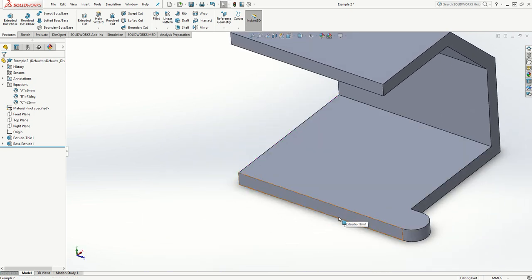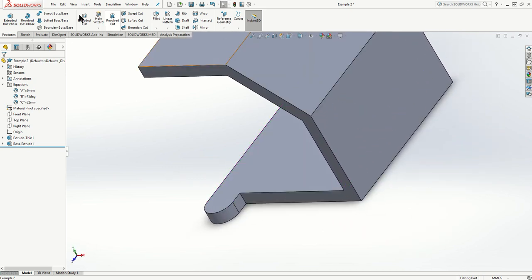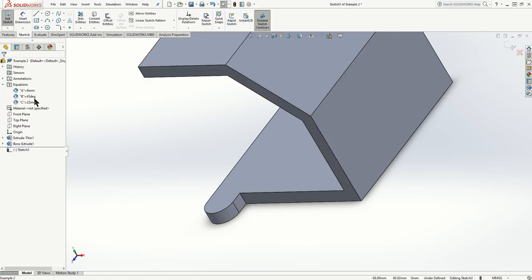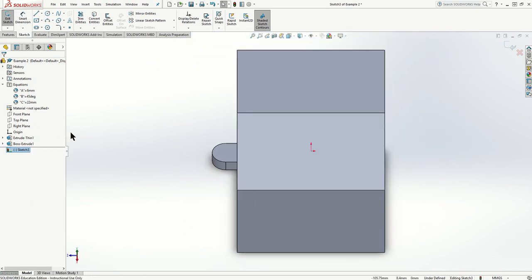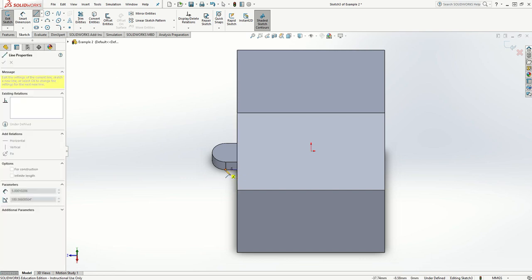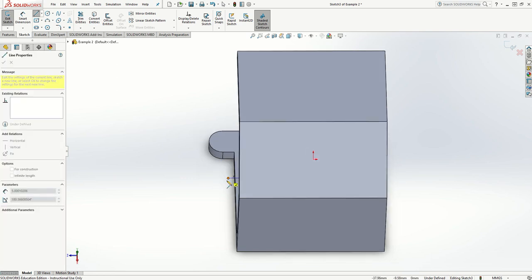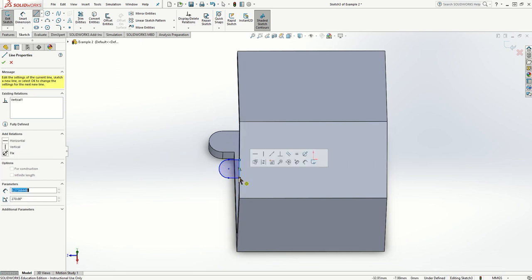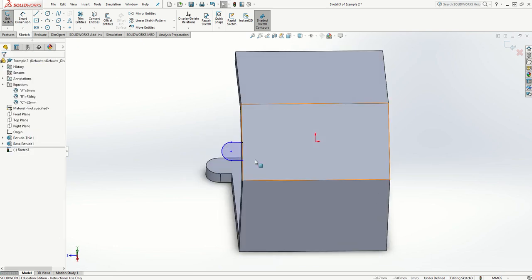Good? After that one's done, I'm going to add the same piece, but I'm going to add it to the top part. So we're going to go over this part, sorry. We're going to do a sketch on this face over here. Let's go now to normal, and we're going to draw the same thing, but with the dimensions that are given. We're going to draw a line, and we're going to go anywhere for now, and I'll place the dimension afterwards. We're going to go from here. Same distance should be 5, correct? 5. Or just don't worry about it. Press A for arc, connect it, and then connect the line and bring it back down. So now we have the same piece that we did at the top.